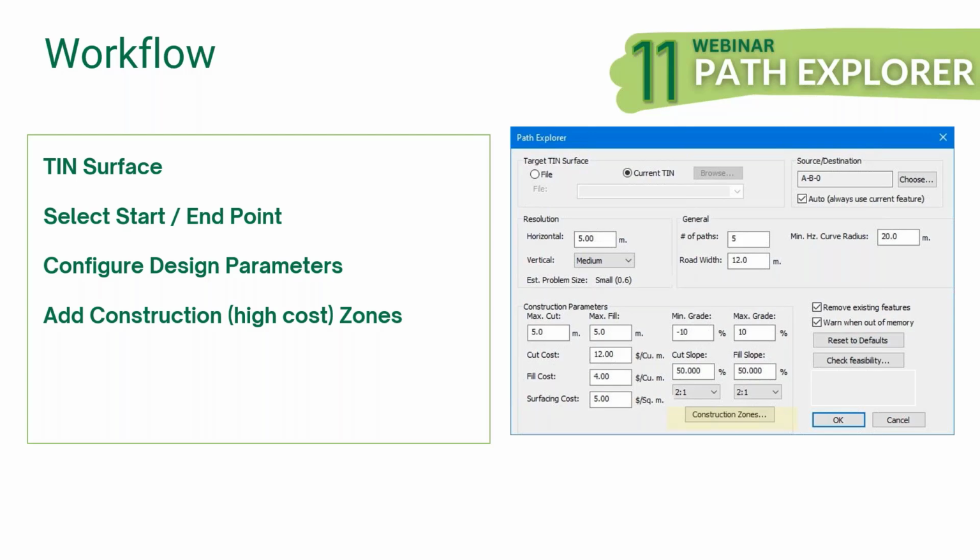And being able to, first use hydrology tools to locate those streams and ponds, and then being able to include an additional cost to cross those, whether that be, say, the cost of adding a culvert, or if it's a major stream or river, you might need to add a bridge. You're able to account for even a larger cost on that specific set of different polylines.